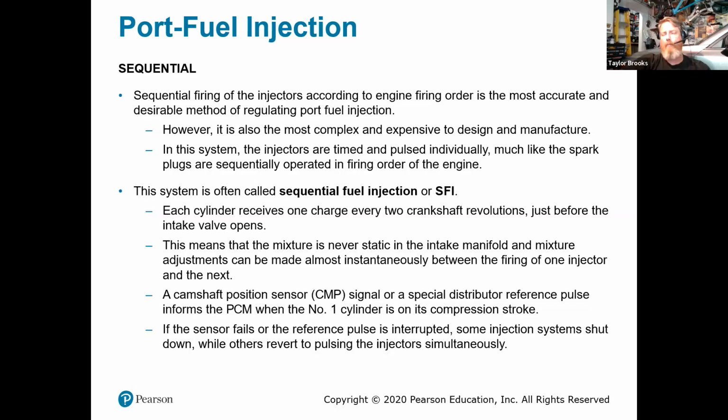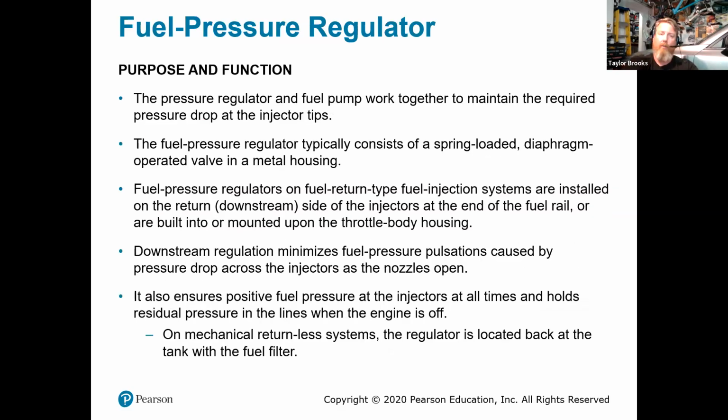Now, the important thing to remember with this type of system is the PCM does have to have the computing power to be able to pay attention to all of the cylinders. So if we have a V8, for instance, we're paying attention to firing the injector right at the point that it should be when we're at the intake stroke, and that intake stroke is going to be different for all 8 cylinders in those 720 degrees of revolution of our crankshaft. So our camshaft timing is going to be really important for our sequential fuel injection design.